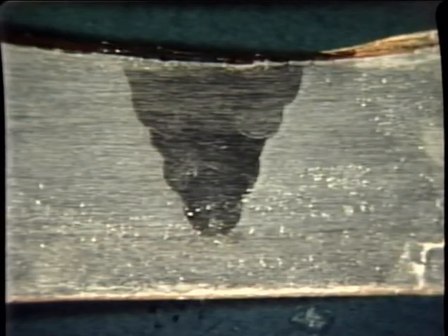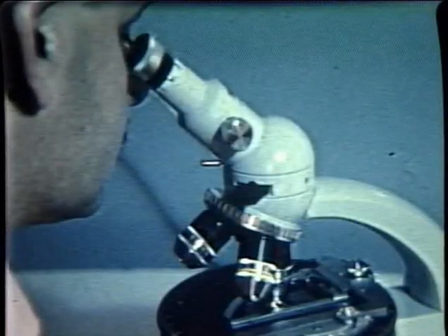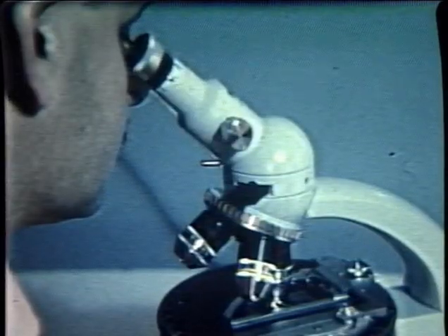Destructive tests are also used to evaluate metallurgical structure. One method consists of cutting a specimen, polishing the cut surface, applying an etching acid, and visually inspecting the etched surface. Variations of the process include viewing the surface with different degrees of magnification. This could range from visual inspection with the naked eye to 250 times or higher.